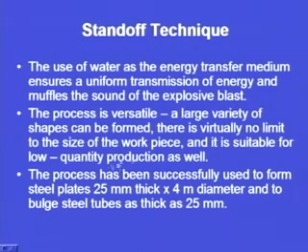This process has been used to form steel plates 25 millimeter thick, and it can also be used to bulge steel tubes. Bulging a steel tube means that if the tube is like this, we create a bulge at any particular cross section, even for tubes as thick as 25 millimeter.